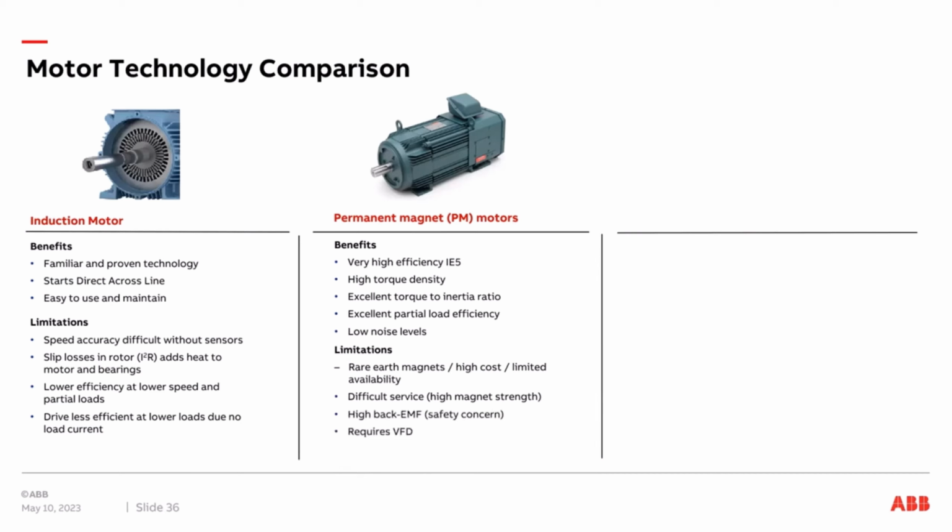It's difficult to service because of high magnetic strength, and high EMF is a safety concern. These permanent magnet motors can produce high electromagnetic fields that can actually be high voltage that can hurt you. VFDs are also required in order to operate most large permanent magnet motors.